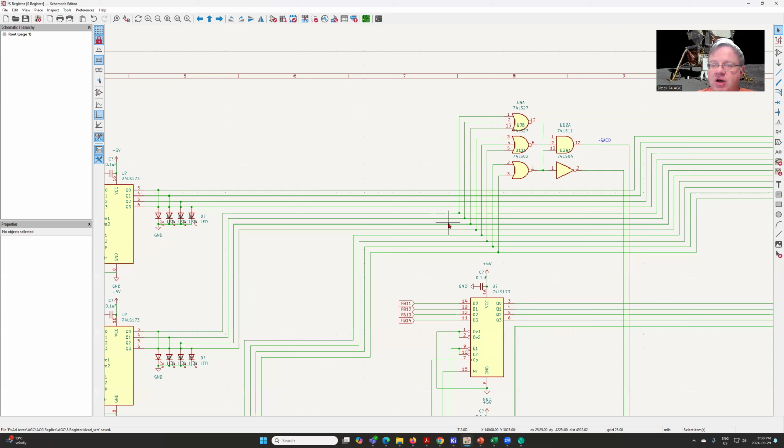Basically, we pull off lines 1, 2, 3, and 4, so basically the first 4 bits, and then we've got the rest. We're basically saying, if we have any bits set here, we're reading an address at octal 0020 and above, which, because of some of the special registers and special addresses, we don't want to write to and from memory in that particular case.